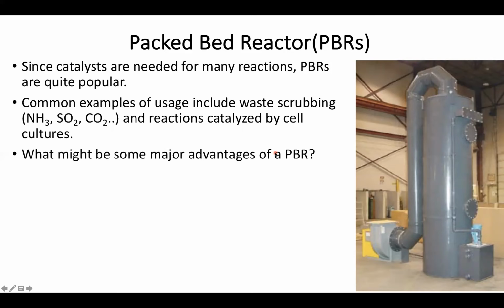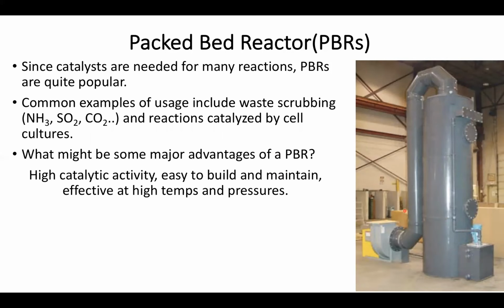Now, we can start to imagine a lot of the major advantages of a packed bed reactor. Let's be honest, a packed bed reactor looks a whole lot easier to build than a CSTR. Another major advantage is that it tends to be a lot more effective at high temperatures and pressures, because the whole system is essentially built for flow.